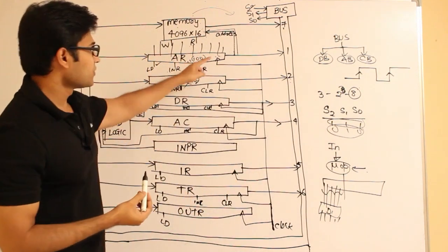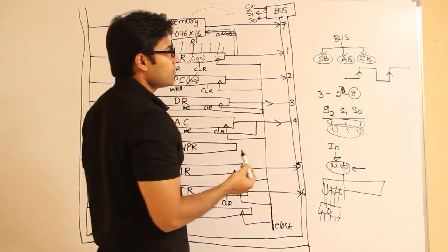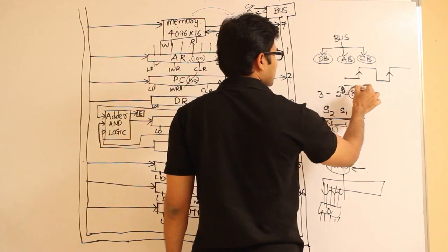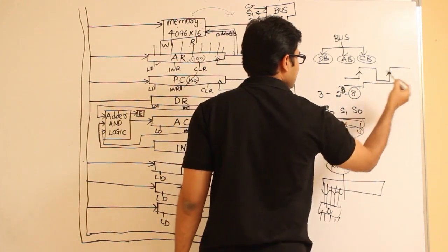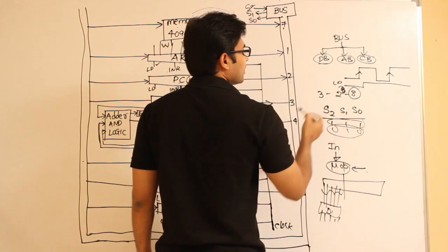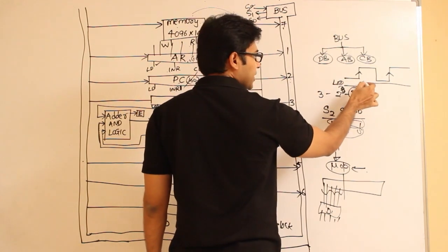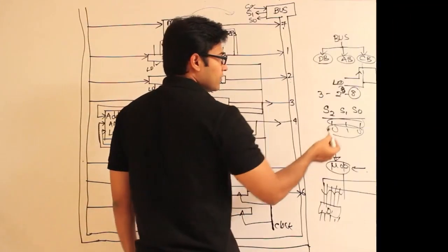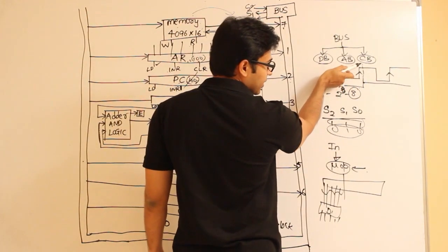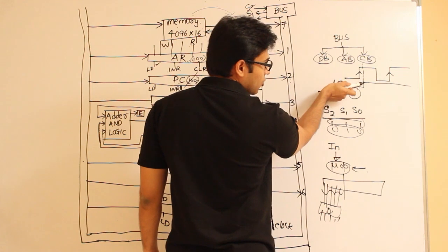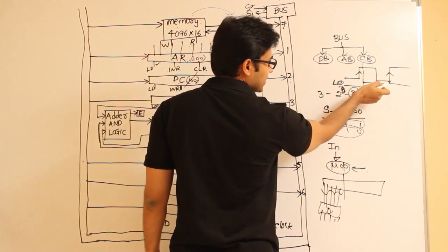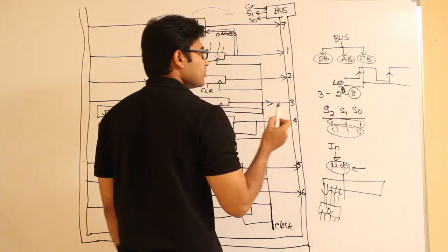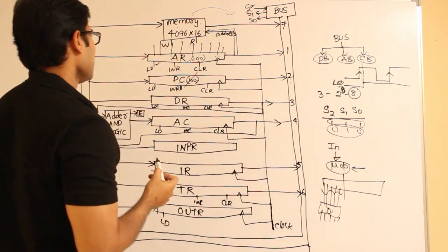So the significance of this one is, even when you switch on, let us say load is turned on here, this is the load symbol, right? The load signal is applied here. Even though the load signal is applied at this point in the clock, load will not happen until this positive edge. This is very important, and you have to observe this one.